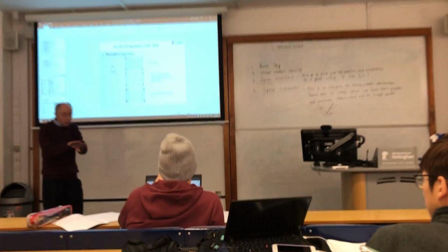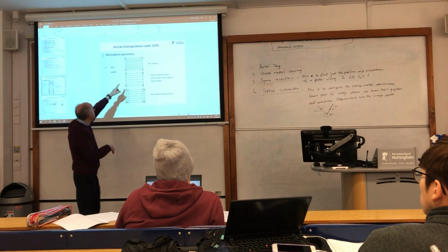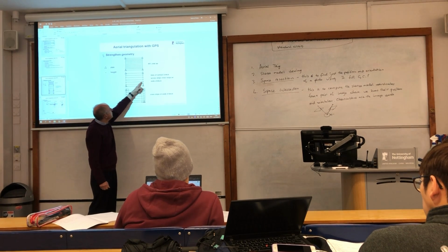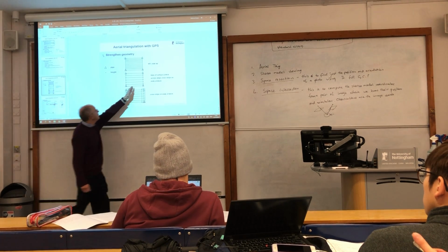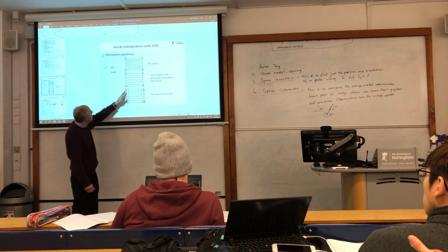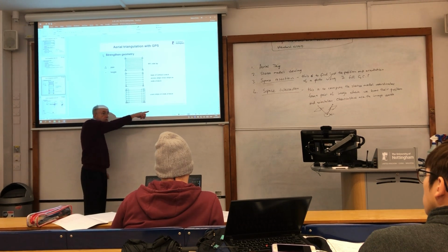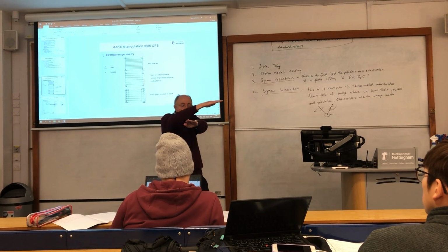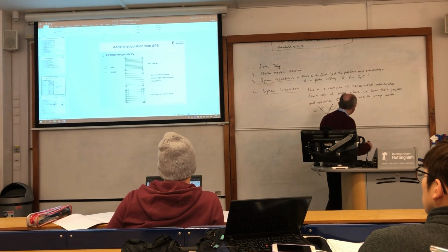We can strengthen the block, which normally has a 20% side lap, by having a bigger overlap. We can strengthen it by running height points, height control points along the ends of the strips, or even up the middle of the strip. Or we could actually fly the strips and then fly 2 cross strips or 3 cross strips, so that you've effectively got the photography crossing each other, and that would strengthen that weakness that you get with the photogrammetric images.